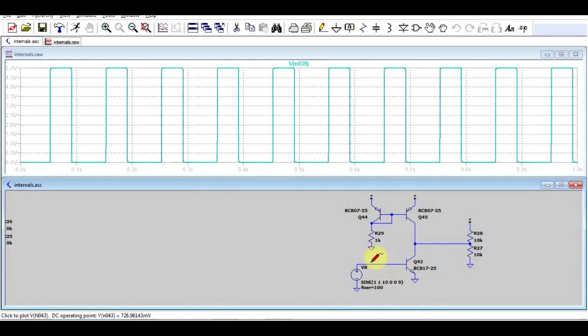So why is that? Well, if we drive our low side transistor with any sort of signal, we will have in the base 0.6 volts more than the emitter, but on the output of the op-amp, the only limitation is coming from the collector emitter saturation voltage. Same thing is happening on the high side. We've got a constant current source, the current is being set using the transistor and resistor on the left side, which drives the base of the high side transistor, but the collector emitter voltage drop again has a minimum value of the saturation voltage.